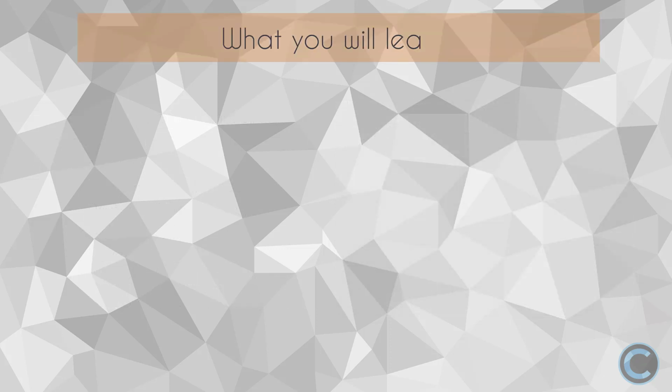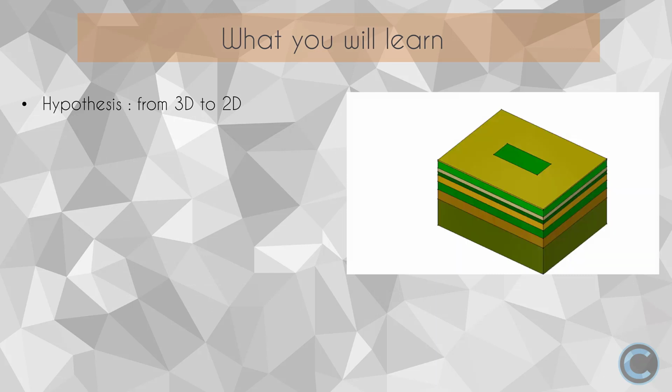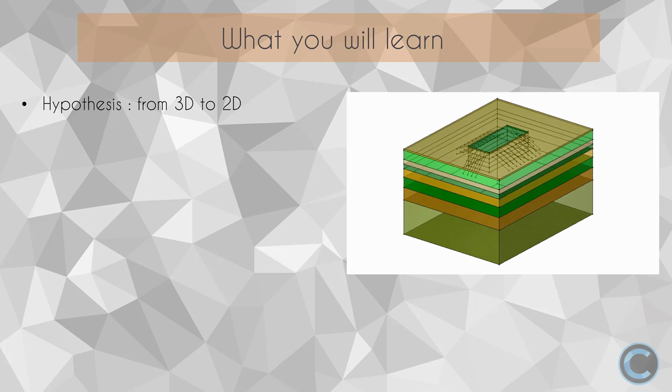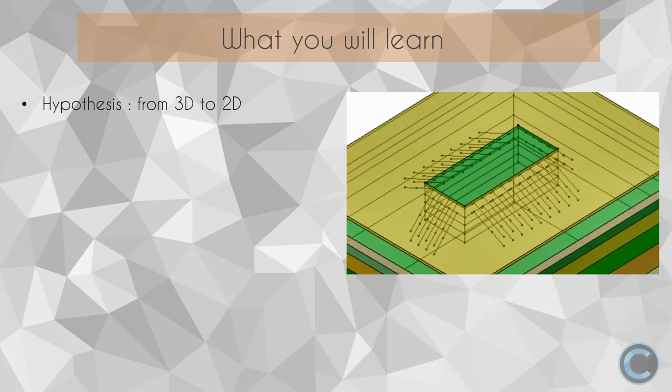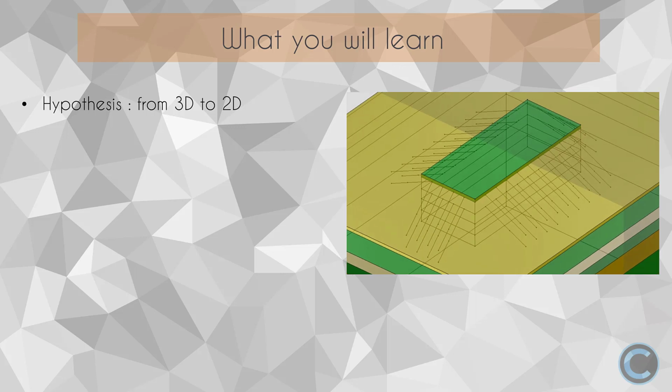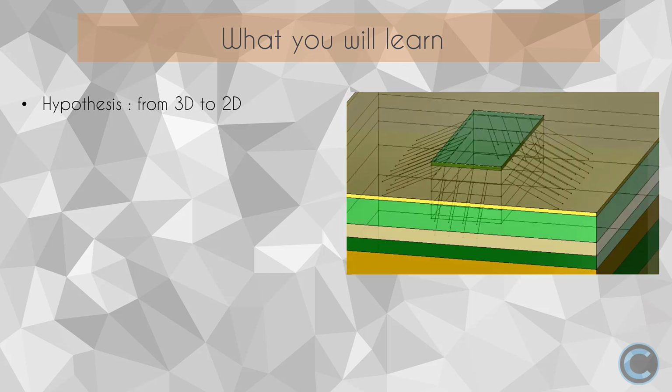First, we explain how to use 2D instead of 3D. The real project to be designed can show preferred dimensions. As illustrated, this excavation is like a box with anchor layers. It is obviously 3D. We can make the hypothesis that a plane section represents the behavior on the width. Thus, we can model this cut under plane strain conditions.